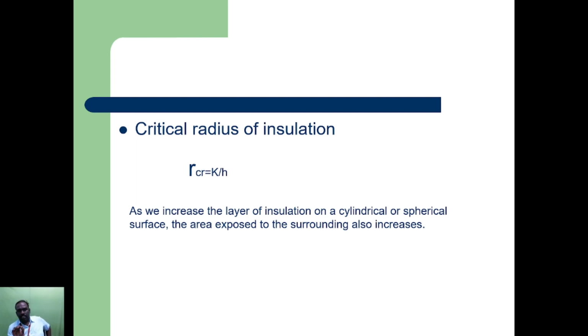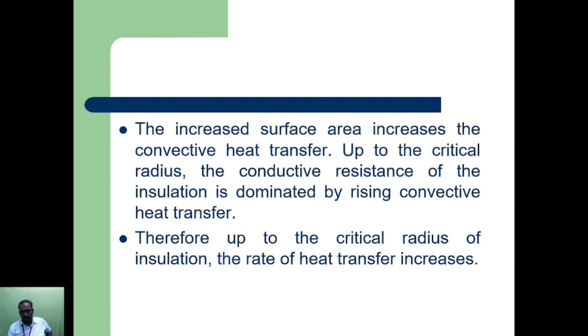For a cylinder, critical radius equals k by 2h. For a sphere, critical radius is 2k by h. h is the heat transfer coefficient, k is the thermal conductivity of the material. That is what we have explained in the critical radius.